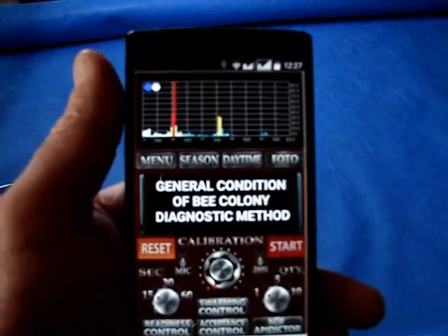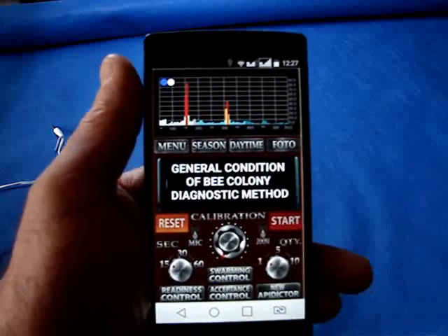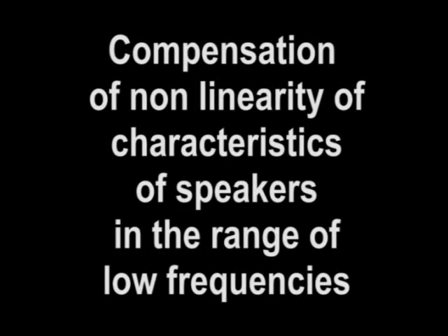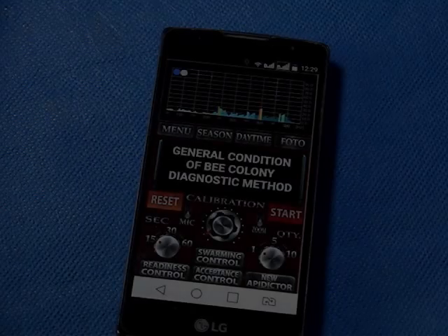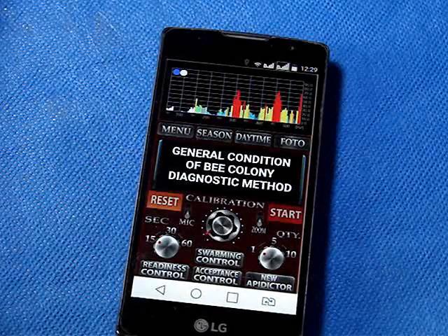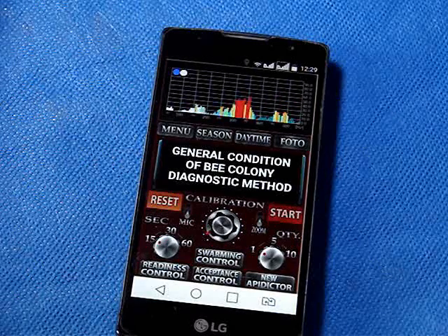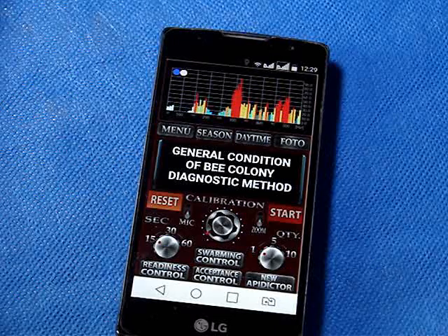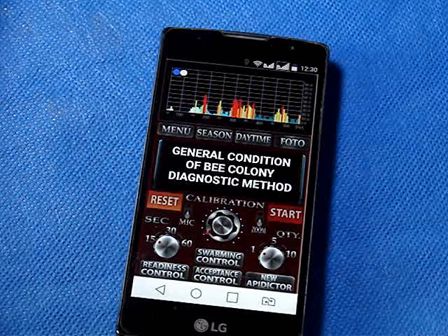All settings are done. Now you can work with this device. But there is one more nuance. The point is that our speaker system is quite good. Its frequency response is linear from the frequency of 65 Hz. Our application analyzes frequencies from 70 Hz, although we start adjusting from 50 Hz. That means, in our case, the last left band and corresponding equalizer slider do not significantly affect our analysis.